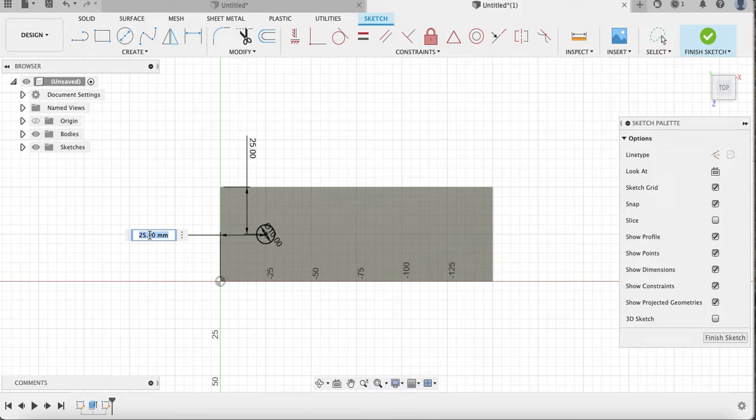Then I showed you yesterday how to create a mirror of that circle on the other side. And what I did was I drew a mirror line in the middle. So I drew a line in the middle of this object because I know that if I use the mirror object, I have to tell Fusion where my mirror line is. So I use my line tool, L. Oh, sorry. Forgot to hit 25, enter. Okay. Now I use my line tool, L.